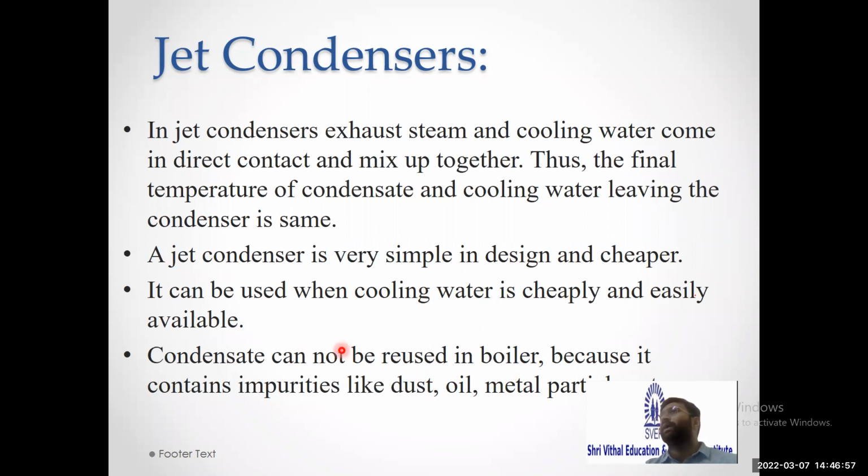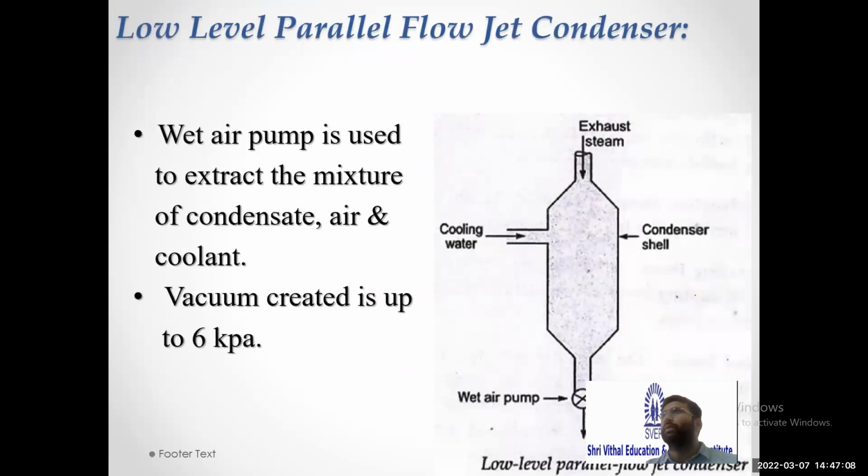So we cannot directly use it for boiler. Again, filtration has to be done, and after filtration we can use it in the boiler. So that is the drawback of jet condenser. So there are some types, we'll see one by one.